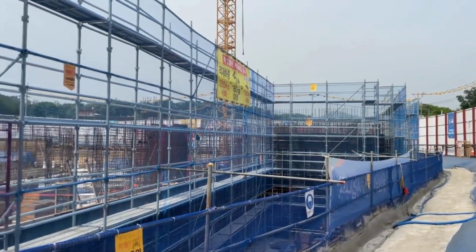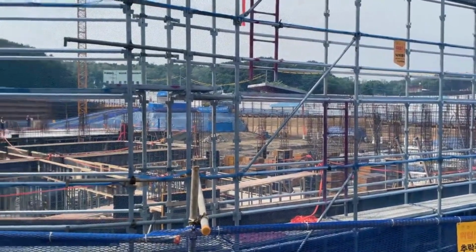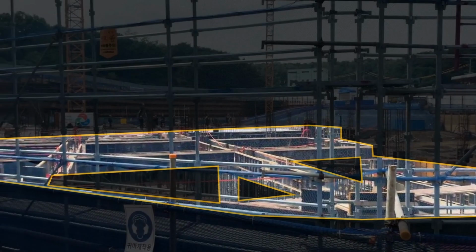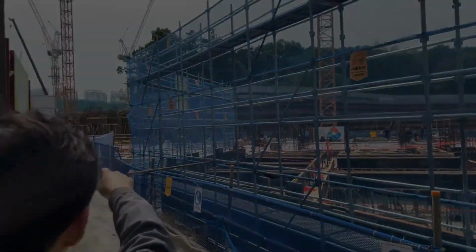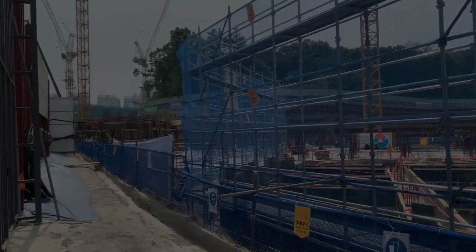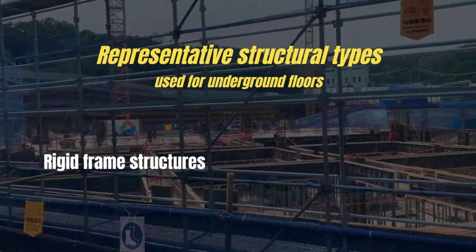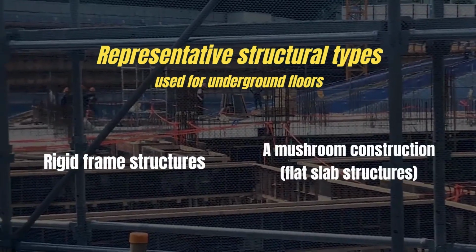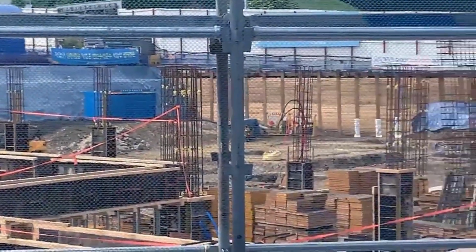As we arrived at the site and opened the construction site gate, we immediately noticed the formwork for column and beam installation. The structure used for the underground floor was a rigid frame structure consisting of columns, beams, and slabs. Rigid frame structures are one of the representative structural types used for underground floors, along with flat slab structures. First, let's take a closer look at these two structural types.